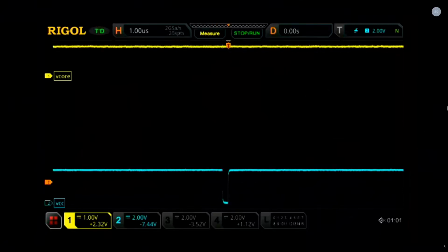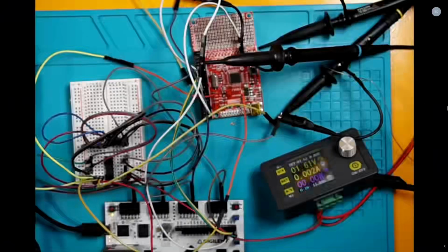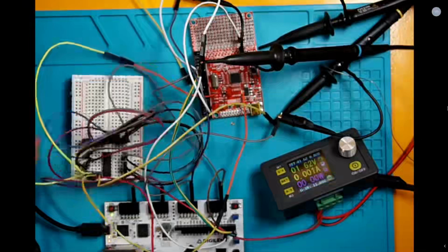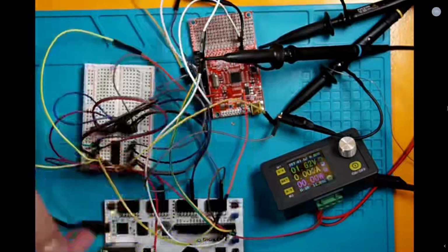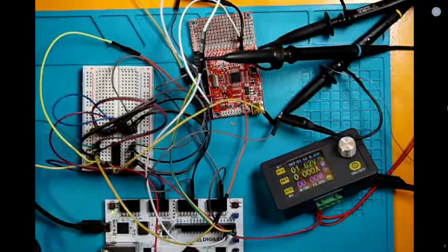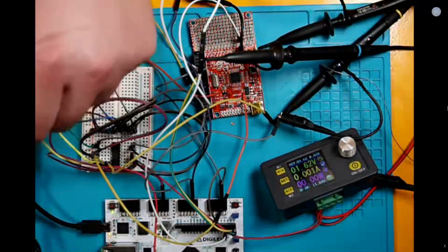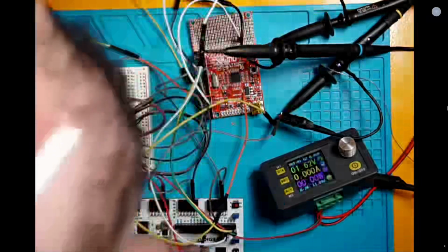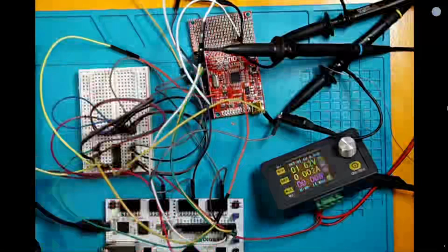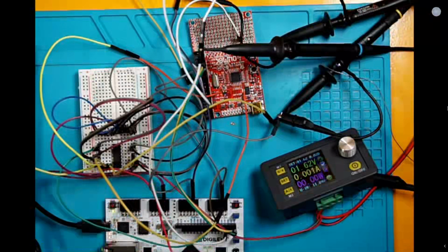So we should also have the glitch signal. The glitch signal currently, we still haven't connected, we're missing one more signal, which is the actual VCC select. So that's on pin 34. So I'll show you me connecting that signal right here. So right now we're going to connect this green wire. We're going to connect to pin 34. So 34 fortunately is this guy right here. Should be this guy on the second header. So let's take a look.